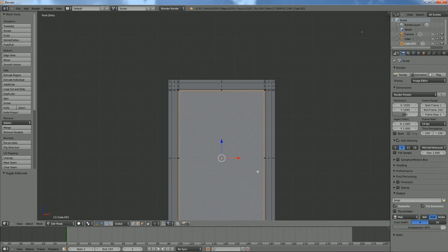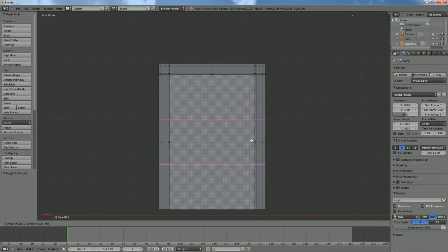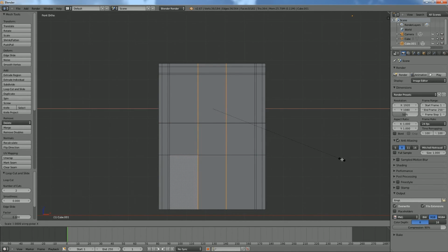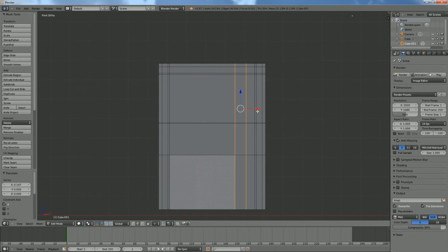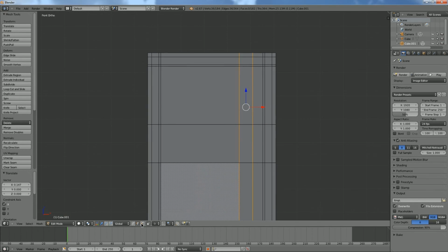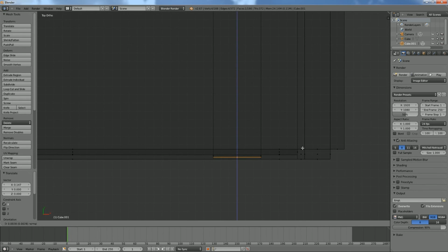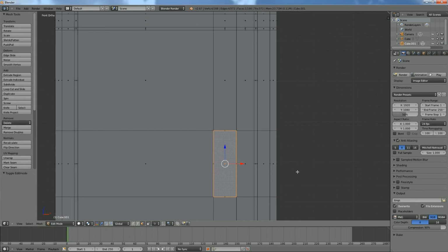And then we'll add the little handle. So we'll go Control R, or mouse wheel up. I'll scale this on the Z, bring it a little bit smaller. About there. Control R here, no mouse wheel up, scale this on the X, it's about there. I'll just bring that over, and then we'll add the handle after we extrude this out. So we'll select that face, 7 to go to top, Z for wireframe, and we'll extrude this out, and then we'll go back to front, go back to solid, and then we'll add the handle parts.